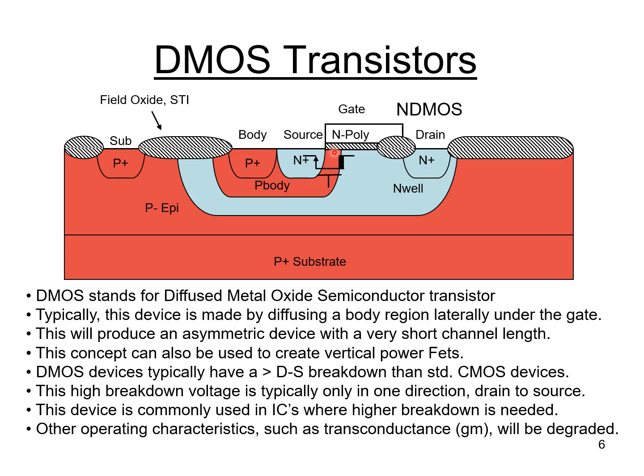And this concept can be used for creating power FETs. That's one of its purposes. In the early days, photolithography was not as advanced, and you couldn't photographically define very small gate lengths. You could still create a small gate length by laterally diffusing one, as shown here. And this was used in the early days to make power FETs.